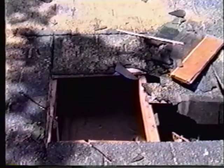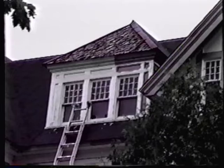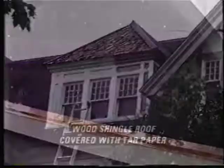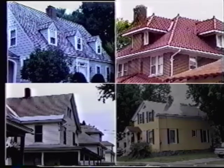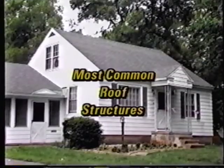Roof decks for buildings with peaked roofs may be tongue and grooved boards, plywood, or particle board. Older homes may use wood shingles on thin lath as roof decking, which presents a very dangerous hazard for our ventilation operation. Covering for the decking includes roofing paper covered by shingles, tile, or slate, and even metal sheets may be found on older homes. There are 5 most common types of peaked roof structures.